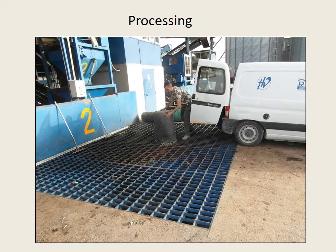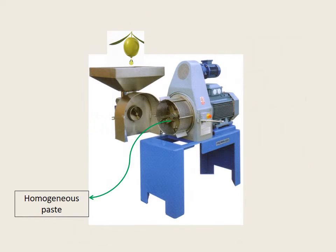Processing the olives consists of several steps. First of all, the olives are cleaned and screened to remove leaves and branches before being ground in the mill. The aim of milling is to turn the olives into a homogeneous paste in order to facilitate oil extraction. To keep the oil essence, this process shouldn't exceed 30 degrees Celsius.